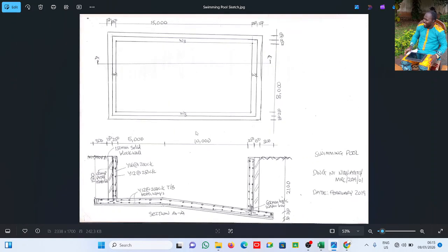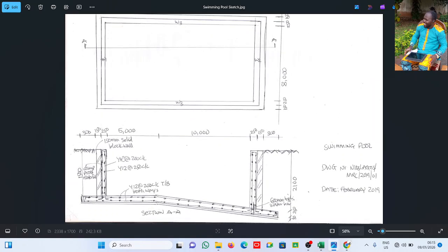This is the plan, right? This is just like the normal land before you start your excavation. Now, I have excavated here. I have put blinding, which was not there before. I have put pool base, which was not there before. What this means is the blinding has displaced the sand there. This pool base has displaced a particular sand, because soil was there before. So the soil displaced by this pool base and that part of blinding will be disposed.